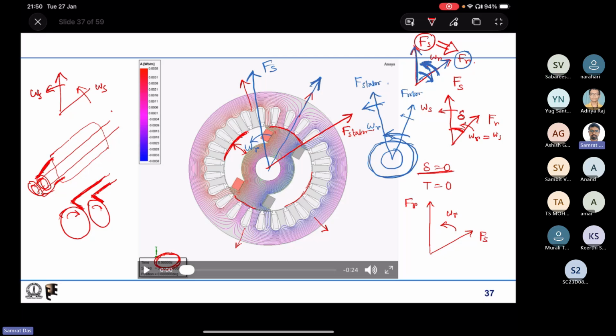What you said is correct. If we are running as a motor, then we excite the stator first. The stator magnetic field will start rotating, and the rotor will try to catch up with it, so the stator magnetic field is always leading the rotor magnetic field. If we do the opposite, then it is generating action.